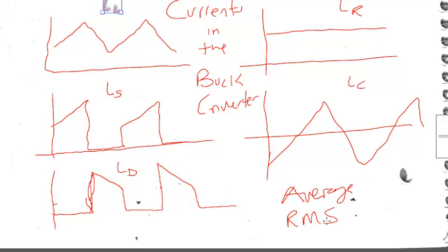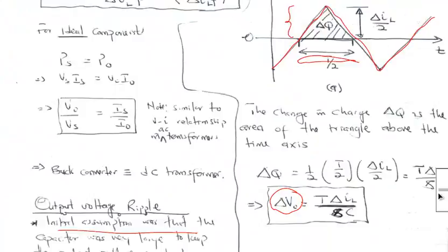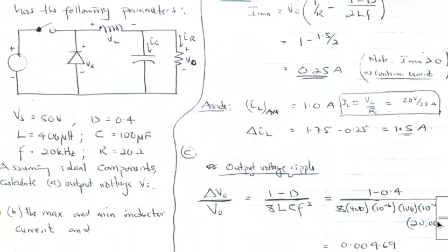Now we are going to go back to take a quick look at our example for today. So over here we have a buck converter. Almost all the elements have been given. So we have Vs, we have the inductor, we have the frequency given. We are operating this DC-DC buck converter at a duty ratio of 0.4. The capacitor has been given to be 100 microfarad, and our resistor is a 20 ohm resistor, a purely resistive element.